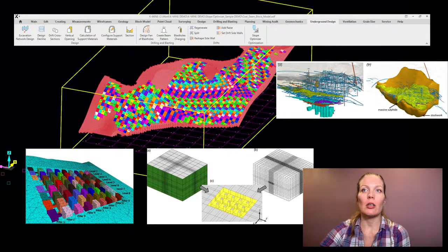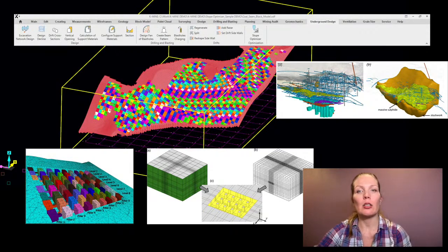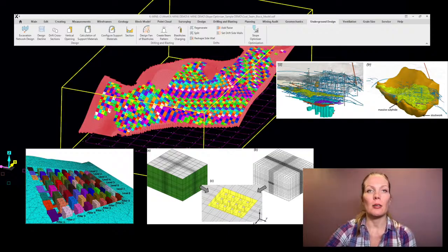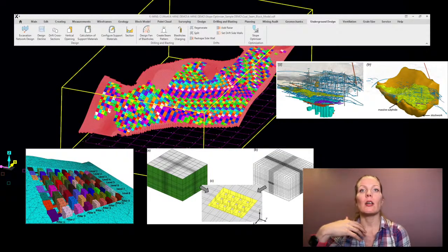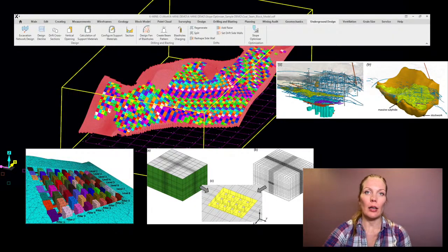First, lock in the mine grid, the discretization used by the project, whether it's 15 by 15 by 3 or 20 by 20 by 4 or another scheme, and then evaluate cell economics using the same discretization. When optimization operates on the same cells that appear in the design model, integration becomes seamless instead of a geometric correction exercise. Well-structured K-mine workflows follow exactly this approach. Optimization runs on clusters aligned with the mine's grid steps rather than on isolated blocks, ensuring the outputs are immediately compatible with the real underground layouts.